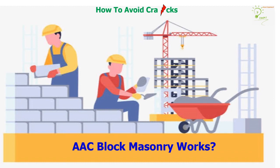Nowadays, in most of the construction or real estate projects, AAC blocks are being used as wall units due to its multifaceted advantages. It reduces cost and time of construction considerably compared to conventional clay or fly ash bricks, with many other advantages. But the interesting thing is we just can't copy an AAC block and paste it in place of our earlier used conventional clay or fly ash brick.